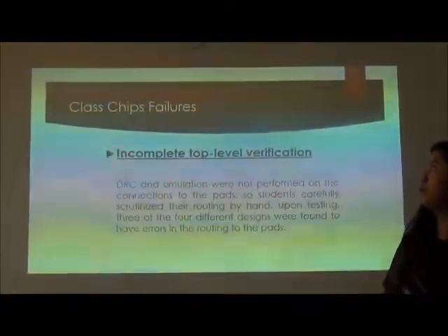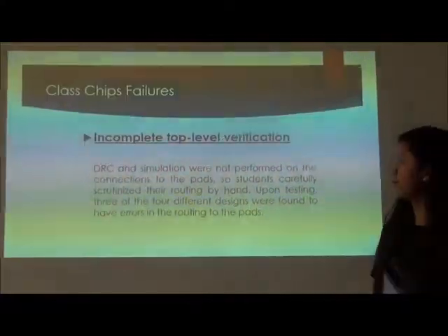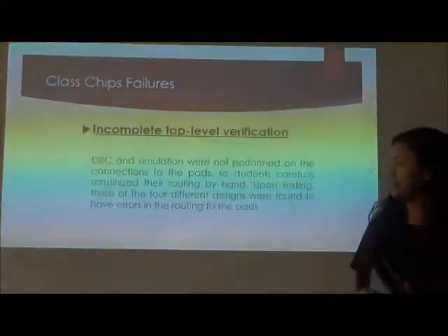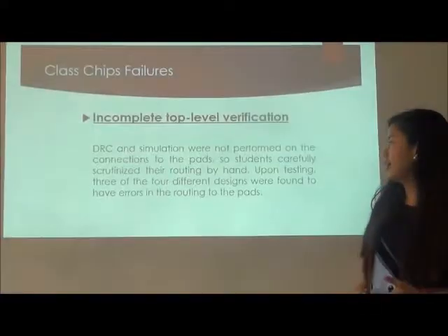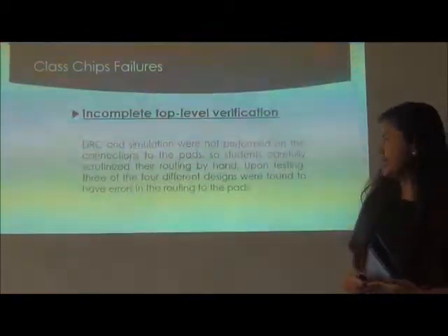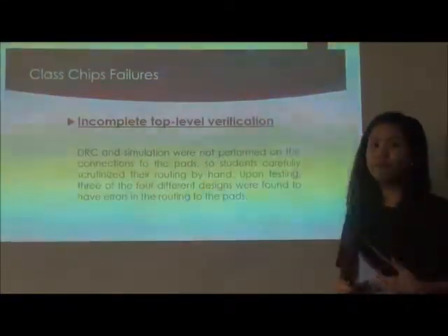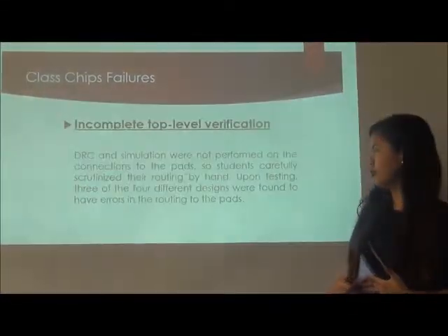Incomplete top-level verification. The RC simulations were not performed on the connections to the pads. So, students carefully scrutinized their routing by hand. Upon testing, three of the four different designs were found to have errors in the routing to the pads.